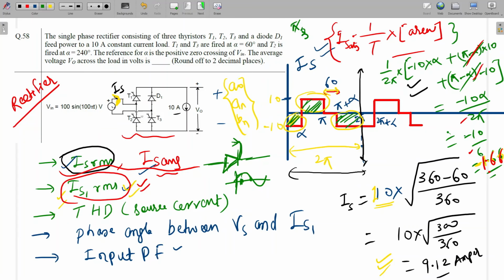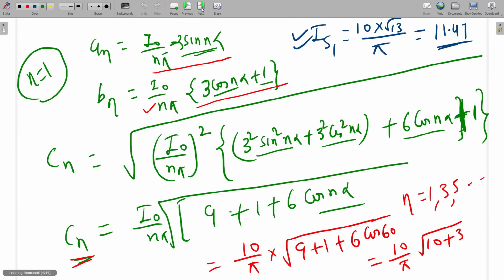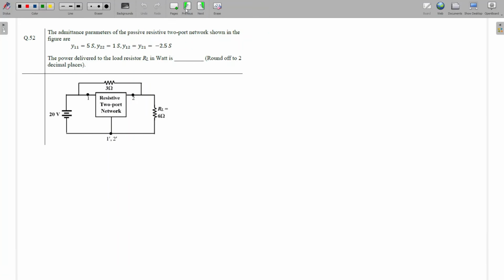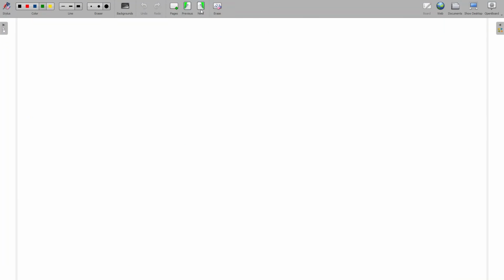So we are believing that T1 is getting some signal, sir. Yes, that's T1. Why is it on? No, no, at that instant we are giving a pulse. See, I will show you. One second. This is the thyristor. Some latching current and holding current will be there. So this is the gate current. Across the gate we are applying some pulses, small duration pulses, from some gate firing circuit.